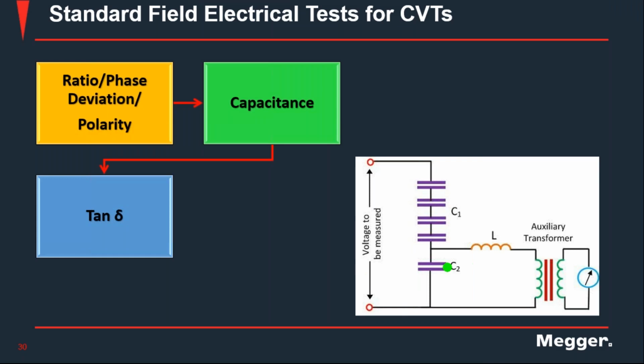There's a combination of switches, of grounding switches here, and you need to understand the constructive part of the instrument transformer to be able to operate those switches properly and test each individual capacitor or each side accurately.